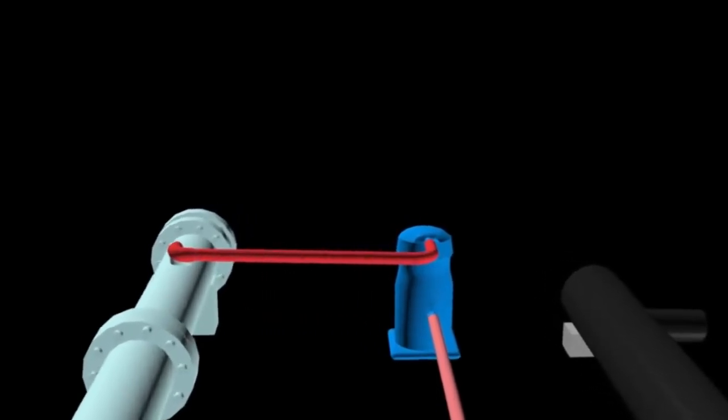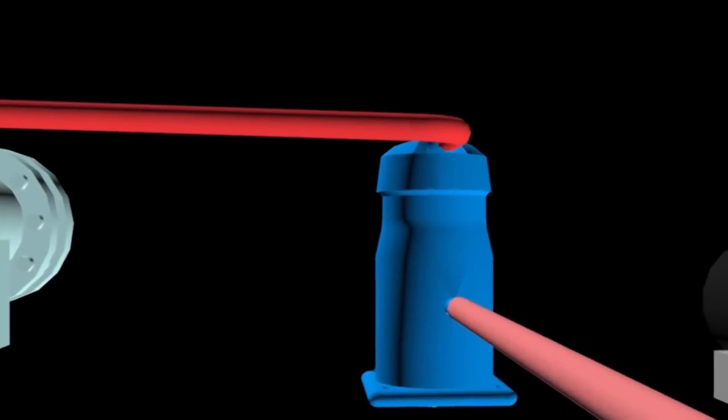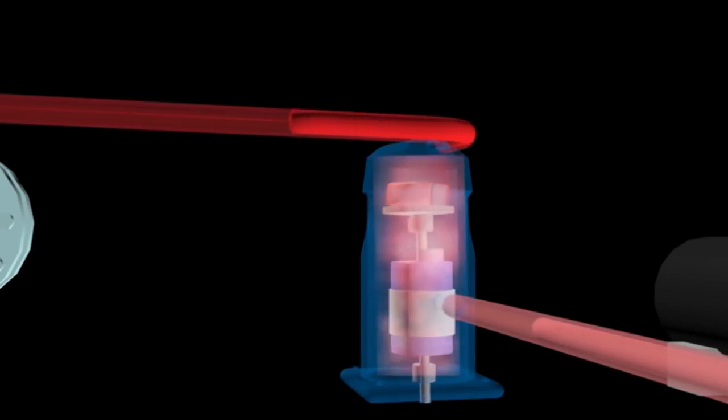In addition, it also serves to increase the temperature of the refrigerant higher than the temperature of condenser water so that the heat transfer can occur in the condenser. The refrigerant enters the compressor as low pressure gas and goes out as high pressure gas. The type of compressor used is scroll hermetic type.